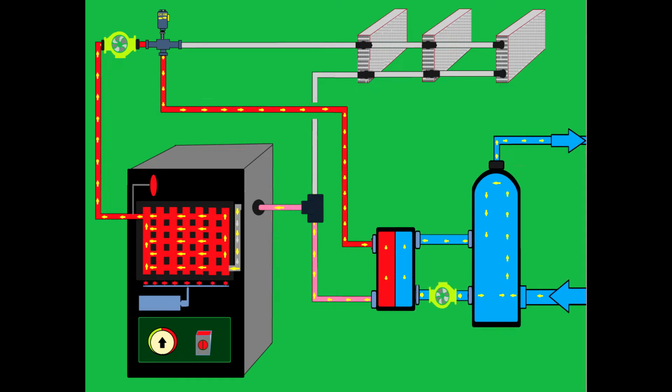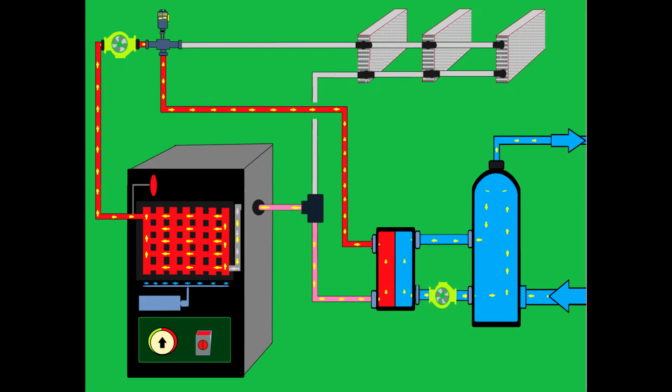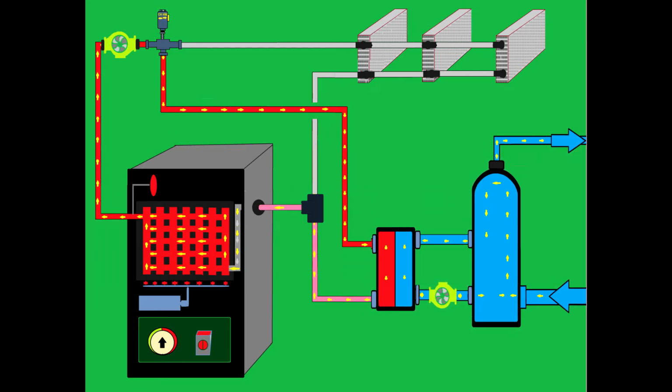This unit has the capability to heat the room, but at the same time it can heat the domestic hot water. You will see the main pump on the left hand side on the top circulating the heating agent, which is heated by the boiler's heat exchangers, while on the right hand side to the lower side you will have a plate heat exchanger, and this is a space which divides the hot water from the heating agent.